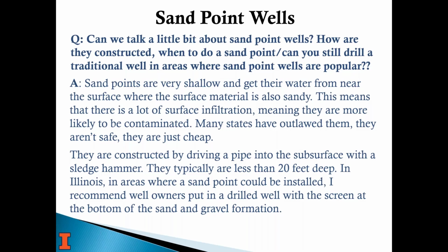I would not ever put in a sandpoint well and would never recommend that to anyone. That's my own opinion, but there's no way to protect it from a spill or anything else, or from what somebody else does. If the water table's still moving laterally towards a river or stream, eventually you're going to get water that's coming from somewhere else. What are your neighbors doing?